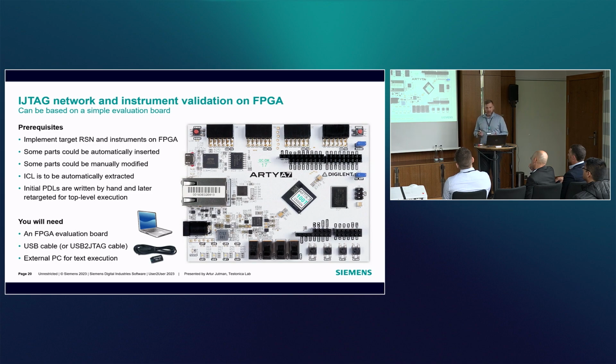Since there is manual interaction, that's another reason why you would like to simulate and validate your design, both in the simulation tools and maybe also on FPGA. But ICL could be automatically extracted, and the initial PDLs would be written by hand for instruments, and then they would be retargeted for top-level execution through JTAG.